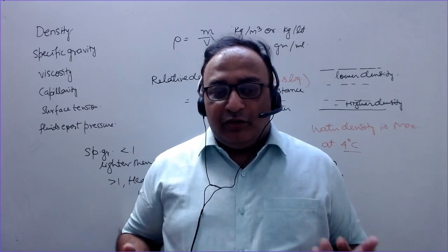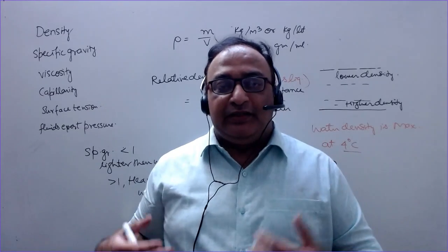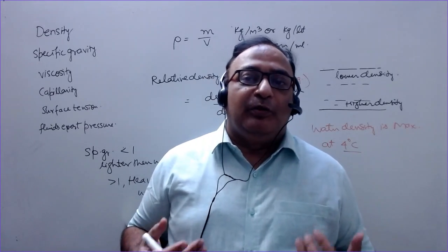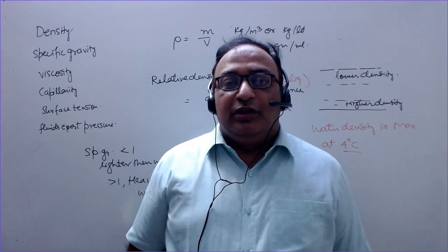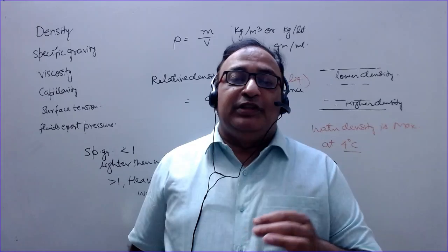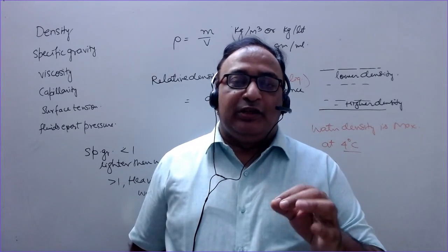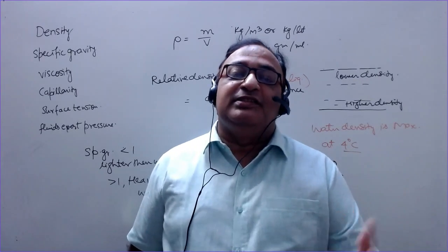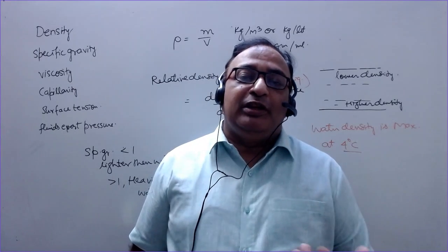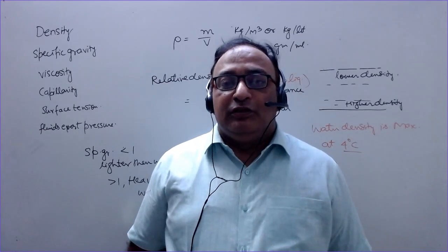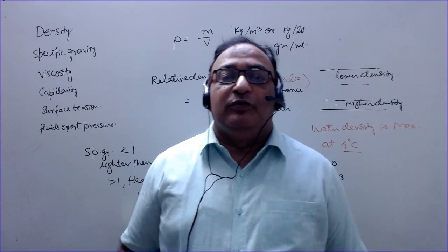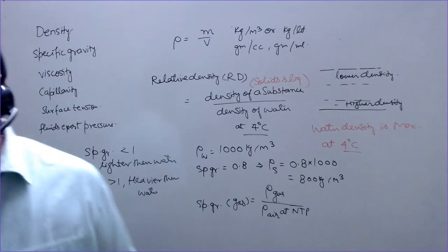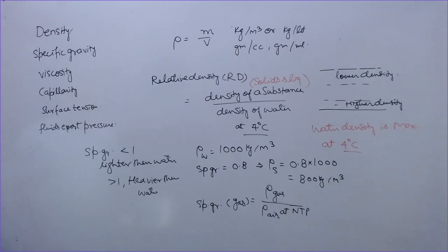So it is trying to move our body from the place which has been occupied by the body, applying a force in the upward direction. That is the buoyancy force. But the weight of that quantity of air is negligible because its density is small. Volume may be large, but density is very small. So we do not experience the buoyancy force when we are moving in a gas like air. So this is the property, specific gravity or relative density.